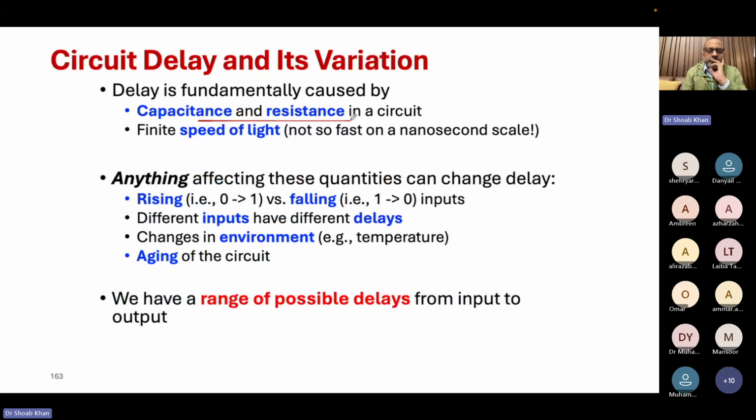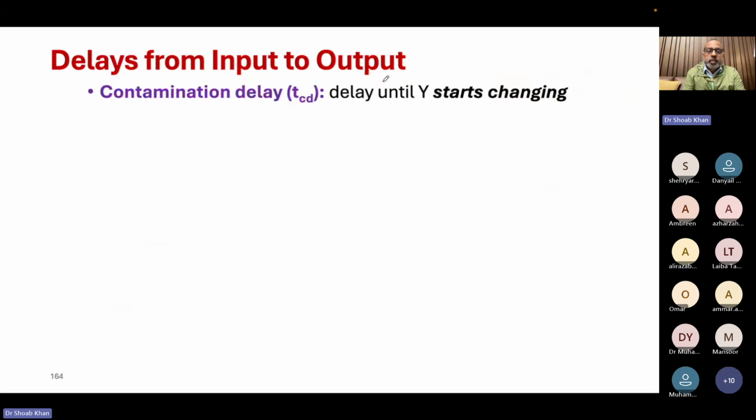And that is where putting a lot of combinational logic into the functionality matters. Just remember this: a lot of combinational logic, like when I was counting the number of comparators, and as they were increasing, the signal going from one comparator to another, to another, to another, will cause a lot of delay, and that will limit how fast I can switch or clock my design. If I cannot clock it faster, then it is a very poor design. So we need to worry about the combinational logic we are putting into our design.